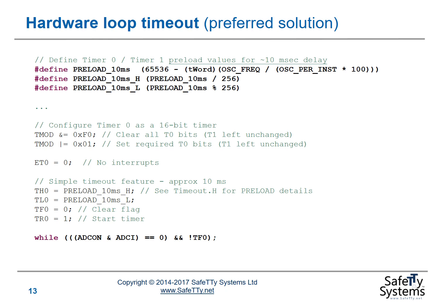So this time our loop is protected. It's no longer a potentially infinite loop, in that now if the A to D conversion is not completed in time, we will have a timeout flag set, and we will have a means of exiting this loop without causing a direct task overrun and potentially a direct system shutdown. So many peripherals need timeout loops of some kind, some kind of timeout mechanism, when they are employed.